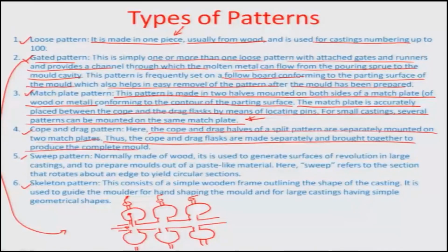So, the difference between a match plate pattern and a cope and drag pattern typically is that a match plate pattern has a single match plate, and in a cope and drag there are two different match plates with different split patterns which you are recombining together.